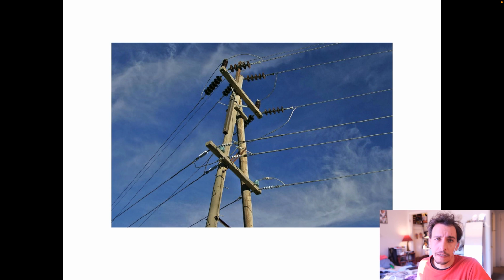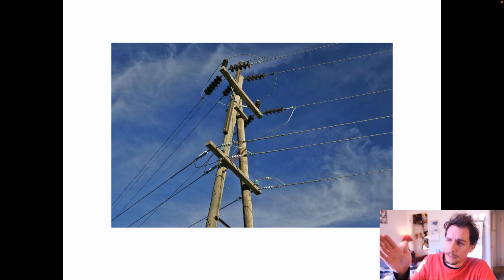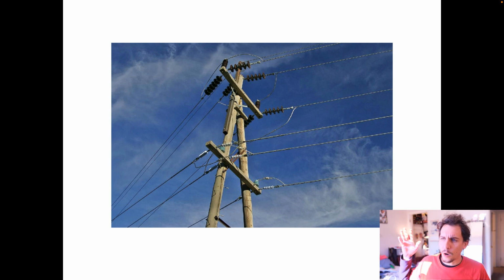Basically, wood is generally an insulator. If it's dry, it does not let electricity pass, but if it's wet, it can. So if we have a storm and our power cable's up there touching that wood, we could get some electricity going down the poles, and it could potentially hurt somebody, right? So you can see that we have these routings of the electrical cable where the cable doesn't actually go through the wood or touch the pole. It goes up and over it. And we have those big, long, wide ceramic discs there to prevent that cable from accidentally flopping down, touching the pole, causing a circuit to become live and hurt somebody.